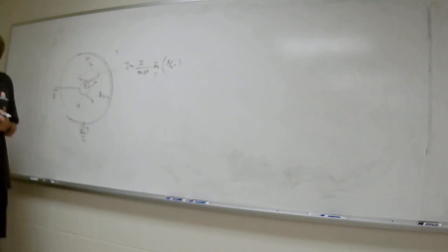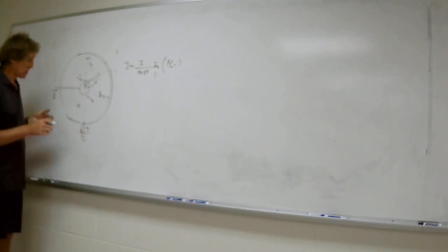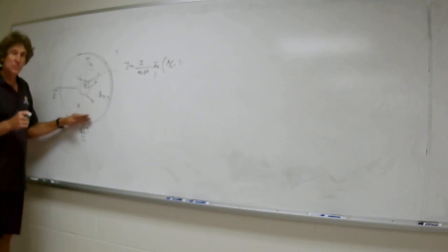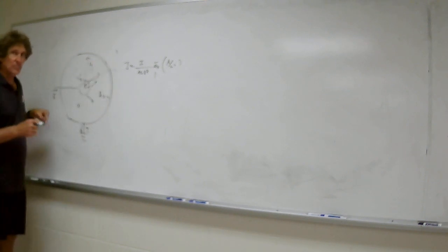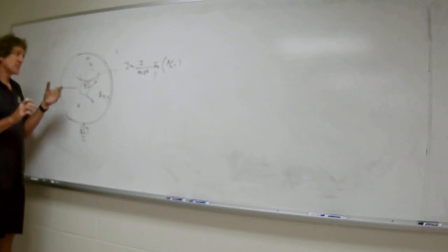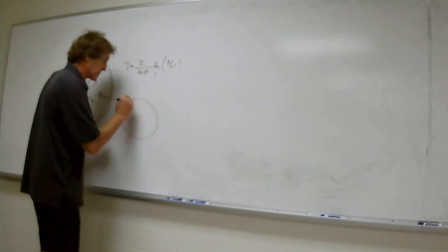Now, the reason I'm saying this, you can make a spherical capacitor like this. You can put a dielectric here, and put a very thin lead in here and charge this inner center and ground the outer shell, right? When you go to discharge this, you will have no inductive energy stored there. It discharges very fast. It's limited by the inductance outside this capacitor. I'm just telling you this for the record. So you may see something like this. It'll be a very, very thin shell. It'll be something like this. See this?